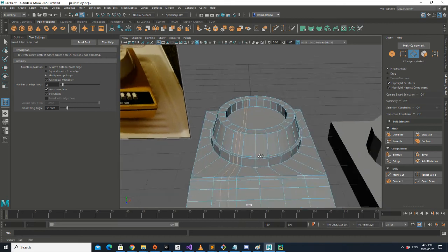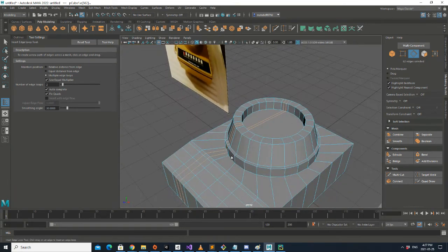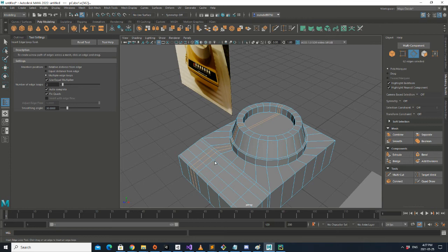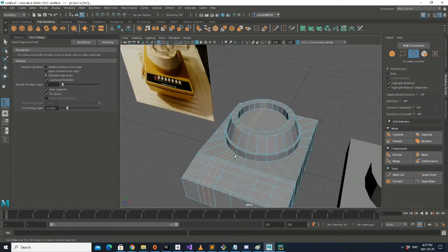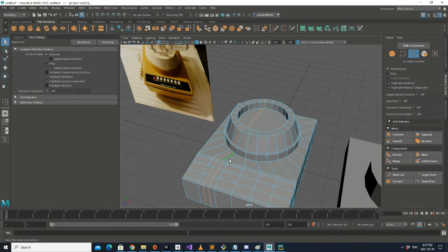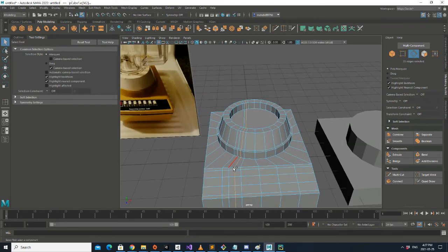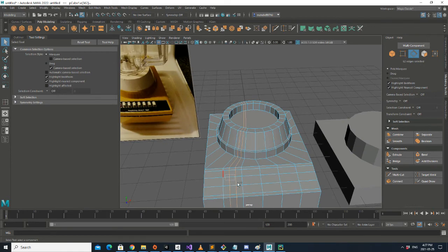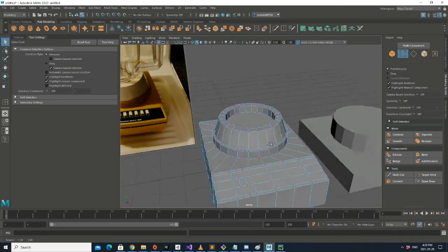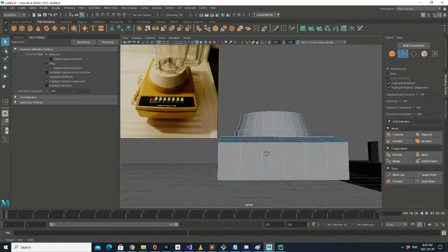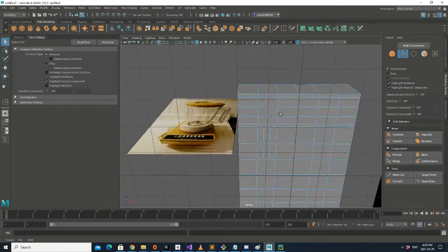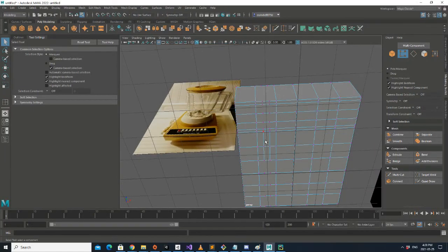Okay, and then what I'm going to do is to select all these edges. So let's just select this edge and this edge, and deselect only these vertices, or even these edges as well. Yeah, and delete all of them. And with that, you will see some ghost vertices here. These vertices should be deleted because they are not connected to anywhere. Oh, these edges should be also deleted as well.